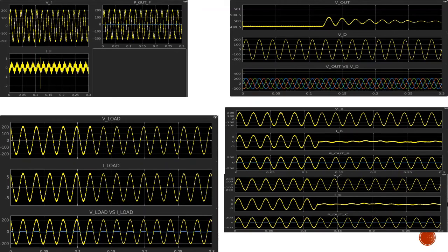If we notice the current and voltage across the load, it is shown that the three phases are delayed by 120 degrees to each other, and the output drops because of the switch, and the increase in the graph is caused by the power flowing in. So when the switch is connected, the power that may transfer to the load is 2 kW, and another 2 kW goes to the inverter, which is the reverse direction. So the total power at the AC side is now altogether 4 kW.